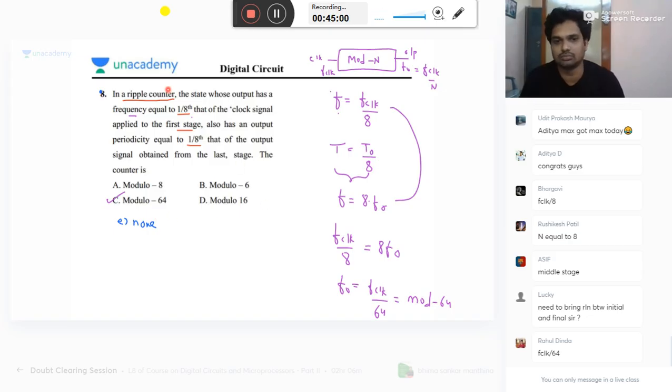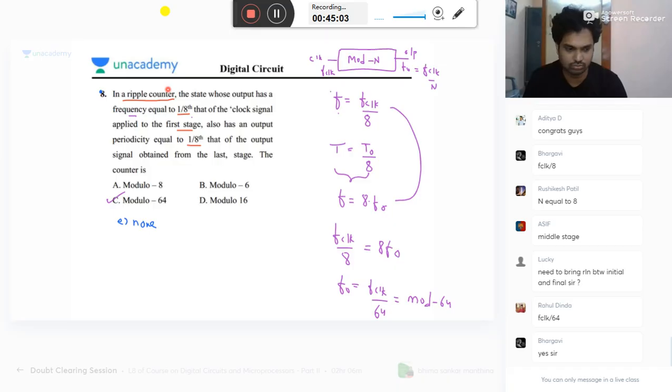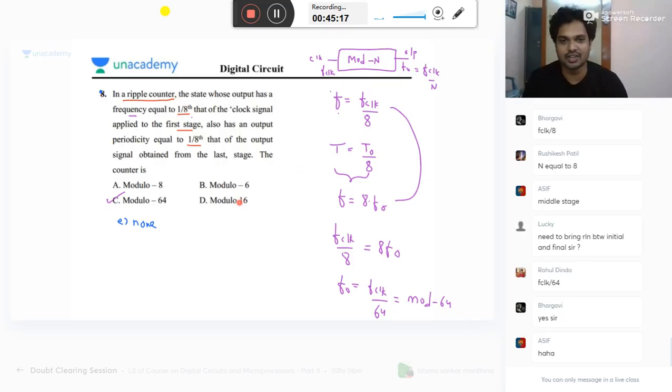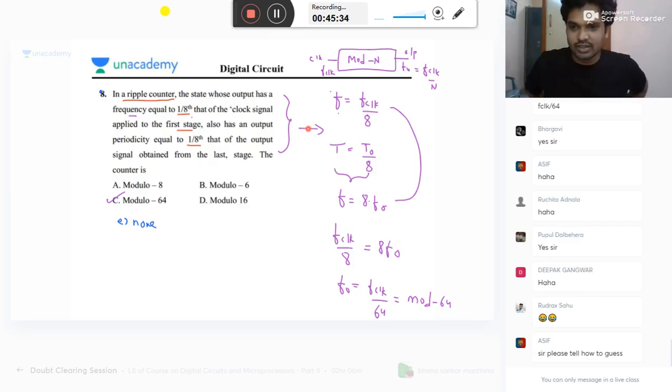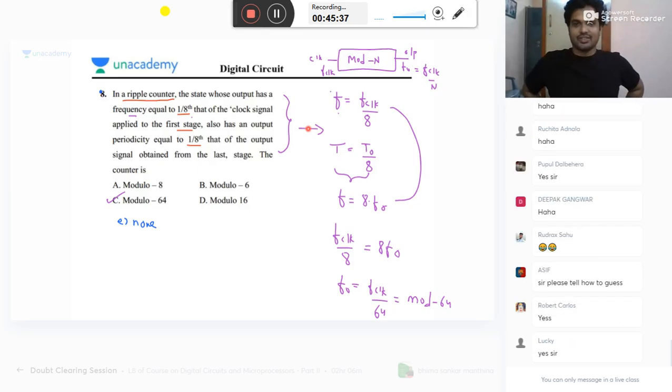You have a shift register shown in the figure initially loaded with the bit pattern 1010. Subsequently, the shift register is clocked. With each clock, the pattern is shifted 1 bit, and with each shift, the serial bit is pushed to the MSB. How many clock pulses will it take again to get back 1010? If you are ready, I will start the poll. Try. I will also try.